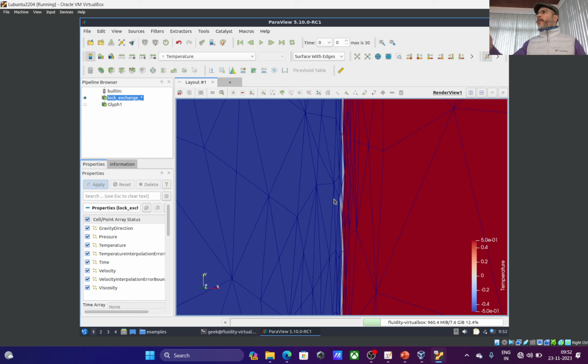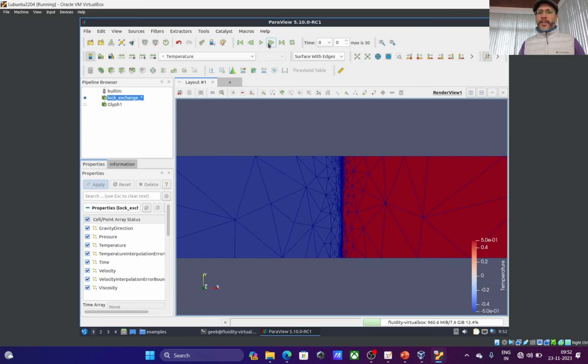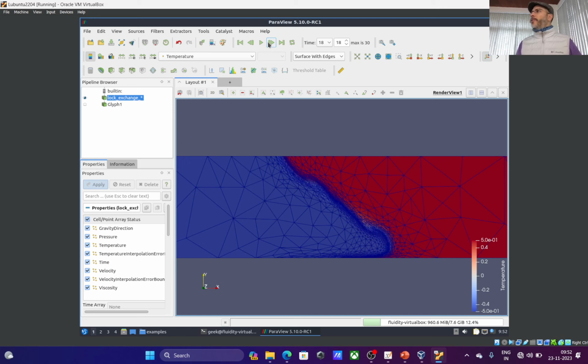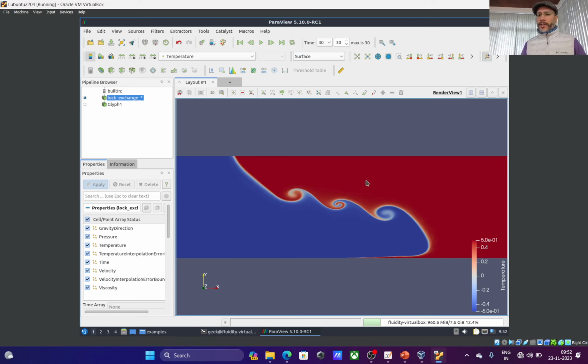It is quite fine in the x direction. It has more number of points in the y direction because there is a boundary. So you'd want to resolve this boundary of two temperatures, so you can actually have an anisotropic mesh to start with, but not just to start with. When the problem is being solved, the mesh is modified. You can see as the flow changes, the mesh evolves. So that is optimizing your computational resources, and that will result in you being able to resolve the boundary very accurately. So you can see these structures are resolved very accurately.